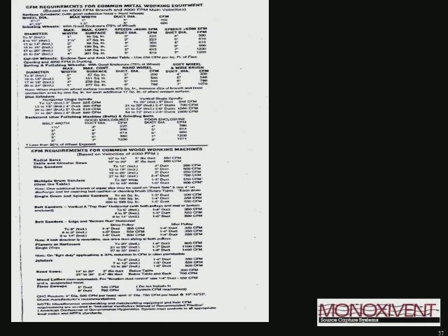A quick example would be, our division manager, Eric Swanson, went to an application one time where the customer was complaining that the dust collection wasn't working properly. What he found was there was a 36-inch wide belt sander, and that typically requires 1,600 CFM just for that. And then there were other tools as well, but the total system design was for 900 CFM. So there was no way that had a chance of being successful in that particular application.